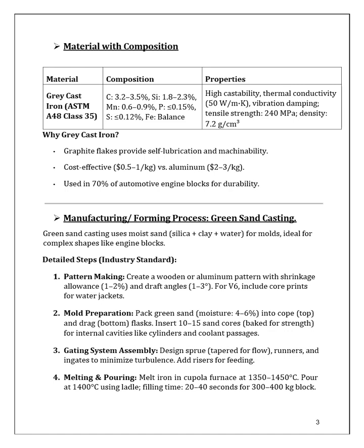The gating system is assembled with a sprue, trap, and runner for minimum turbulence, and risers for filling. Then melting and pouring: the furnace temperature is 1450 degrees Celsius, and the filling time is 20 to 40 seconds. For that, 300 kg to 400 kg boxes are prepared.